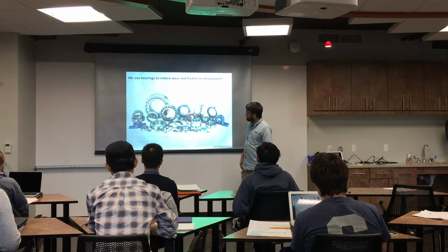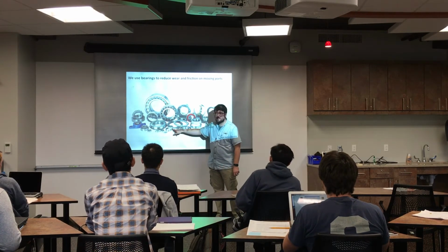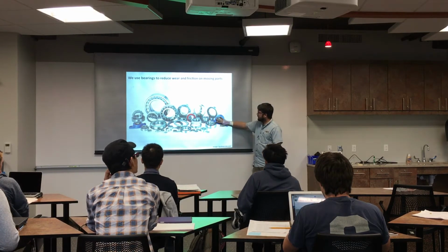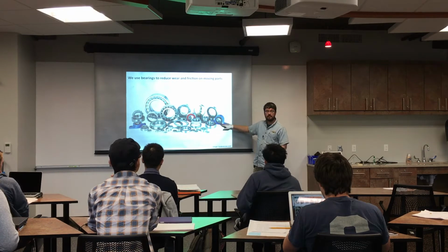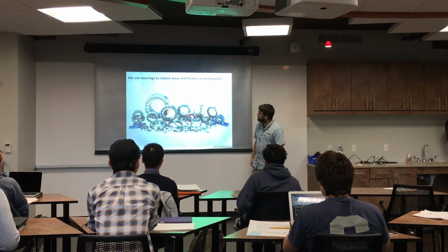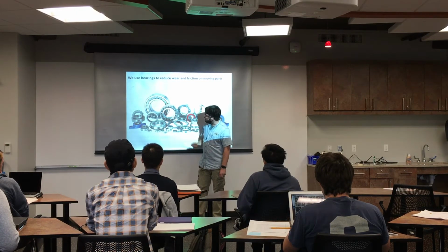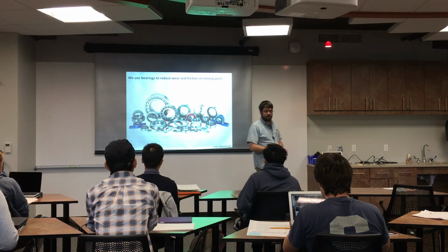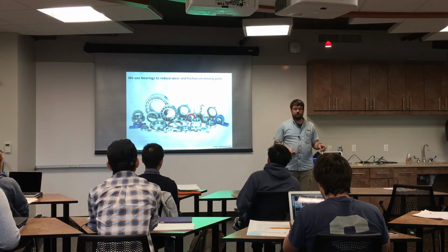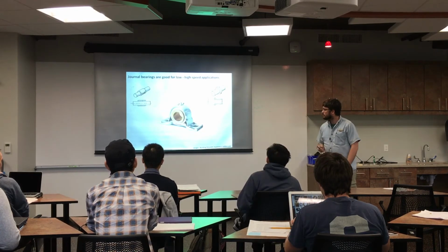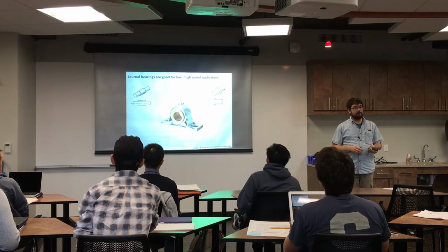We'll talk about some of the types, but just to point out, you can see there's some that are tapered. So they've got these rollers, and they're not straight. They're tapered on the sides. Here are some that are mounted in, these are called pillow blocks, that you can mount down to your base plate for your apparatus. These have these cylindrical rollers. Here's some ball bearings. All kinds of good stuff there. And you should go to, and in fact, we might do this, McMaster-Carr.com or Grainger or MSC or any of these industrial suppliers and look through their bearing selection. It's astonishing.